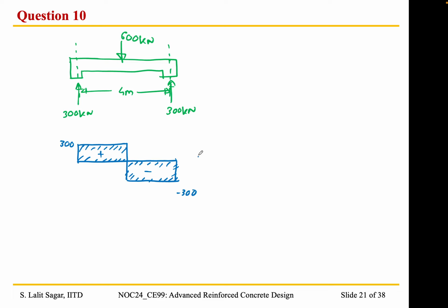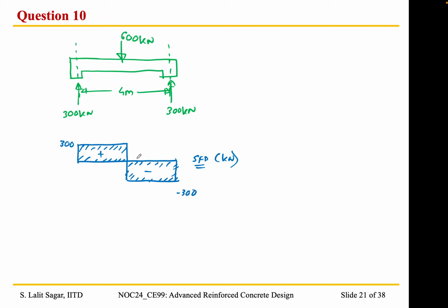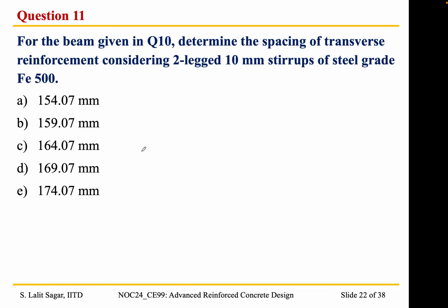So this is our SFD, which is in kilonewton. So the design shear force for the beam is going to be 300 kilonewton. Okay. So now the question is, for the beam that was given in question 10,